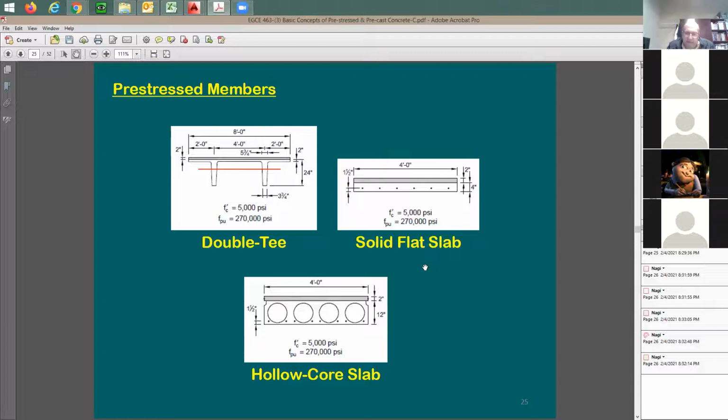Post-tension means that the tension is going to happen after the concrete is hardened. So when the concrete becomes solid, they start to put the tension on it. They do the pre-stressing. The pre-tension, they put the tension on the cables before they pour the concrete.